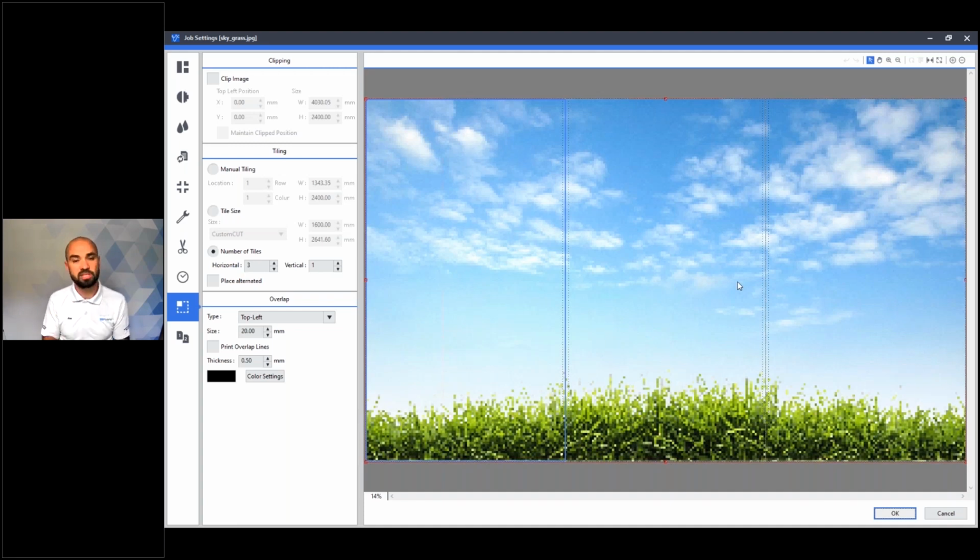The preference is normally down to where it's being put up within a room. If I was putting this into a room and the entrance was on the right-hand side, this normally means that you would start on the left-hand side, so the overlap join is not visible when you walk into the room.